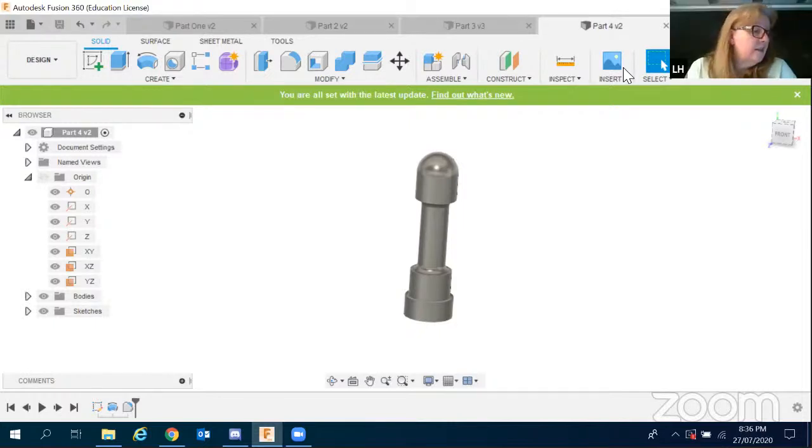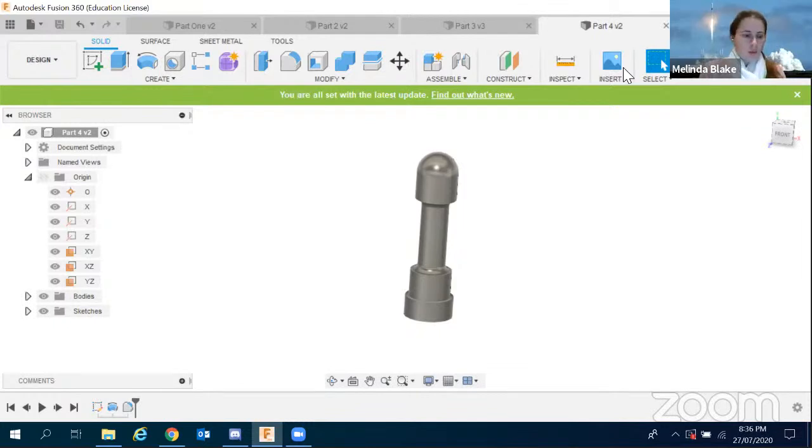We have one more question. How would a low resource team without a lot of machining use CAD to make parts? Without a lot of machining, so I mean, if you don't have a 3D printer, what can you be using CAD for? Well, if you've got different people that are the designers versus the manufacturers, even if you've got no machine tools, it's still a good tool to have, because instead of just handing off a rough sketch to the manufacturing team, the designer can CAD up an individual part or a couple of parts, and double check in CAD that those parts actually fit together before they go over to the manufacturing team.